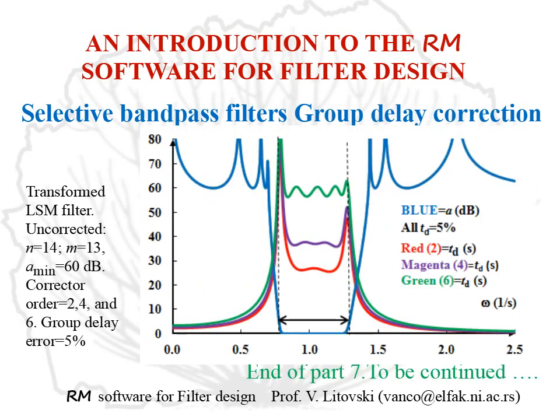And in this final slide we see the same problem, but the group delay error is 5%, and as we can see we cannot go above the 6th order since the whole passband is covered. This ends the 7th part of the series of lectures. Thank you for your attention.